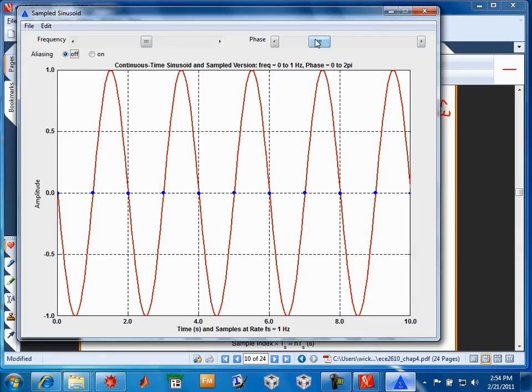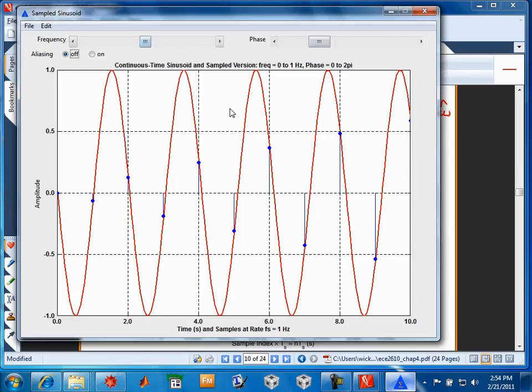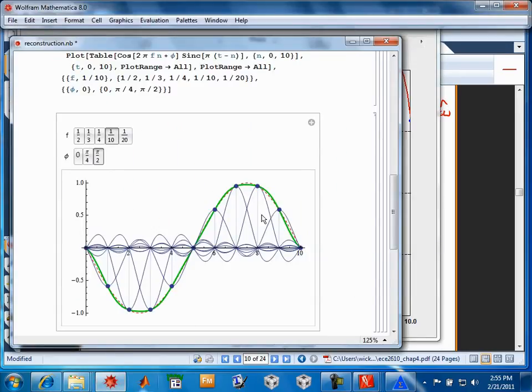But if you sample at just slightly greater, in other words, bring this frequency down, then there's enough samples, and it's due to the asynchronous behavior between the sampling rate clock and the signal that over time those samples will ebb and flow across the peaks of the waveform, and you will be able to reconstruct. And I'll talk more about an example in Mathematica that shows you how the reconstruction works. That'll be probably next time.